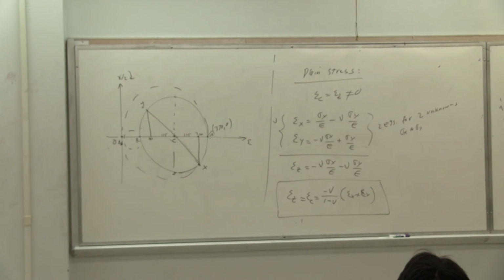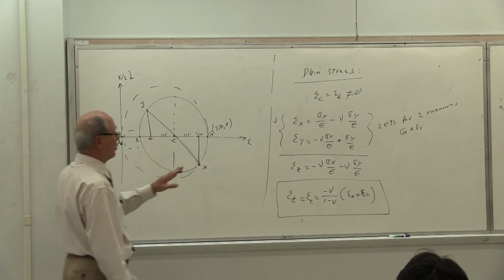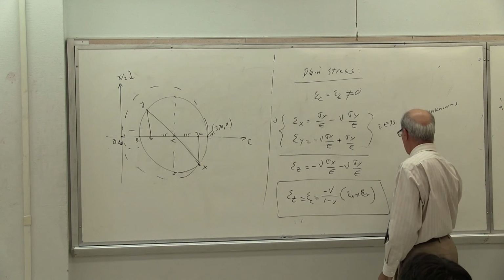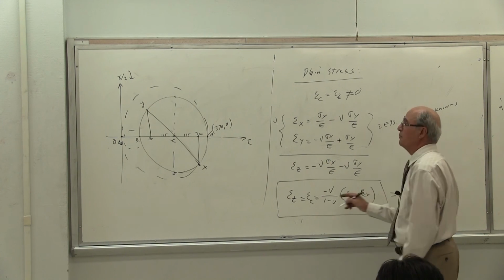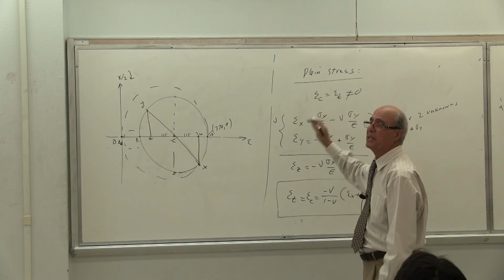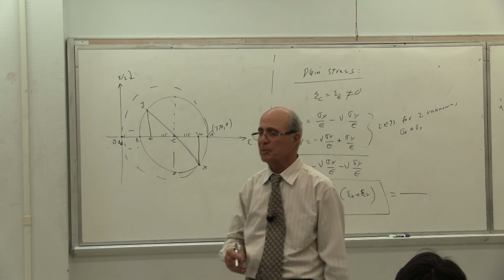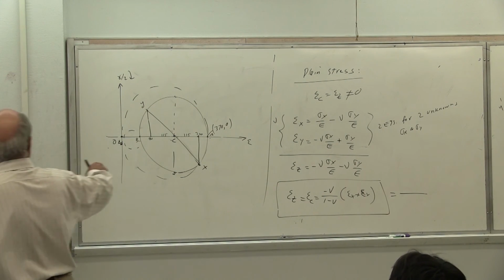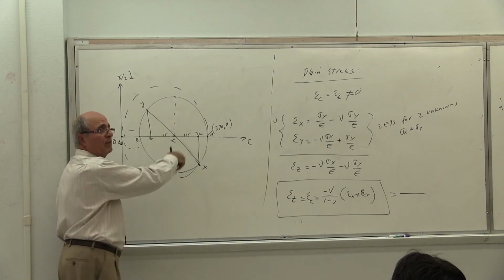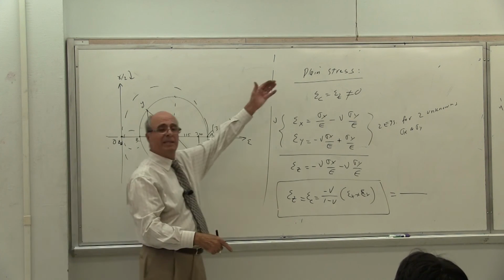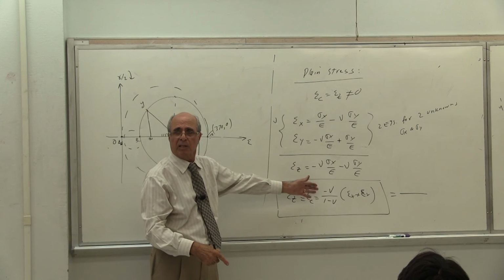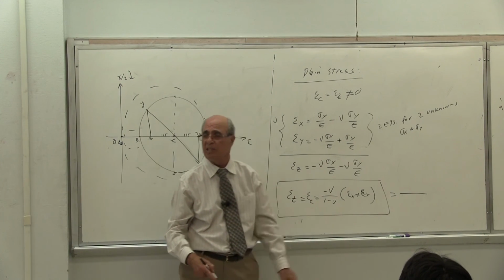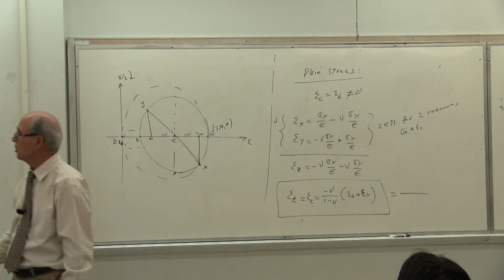So let me finish the problem, then you can ask. For our problem, what's epsilon c equal to? Now let's solve it. Epsilon c becomes equal to what's the value of nu? Notice E was eliminated here. Actually, E drops out because E has nothing to do with it. What is epsilon? That was plane strain. Everybody has stress. And now I'm doing plane stress, correct or not? Then I need to calculate epsilon c. Is that correct? Because epsilon c in plane stress is not equal to 0.